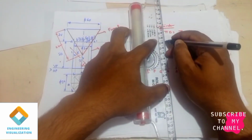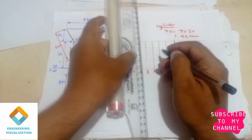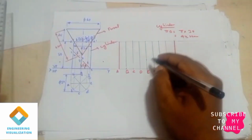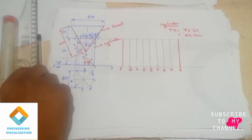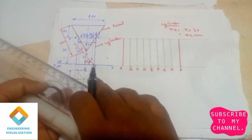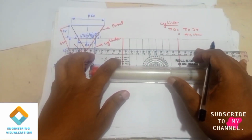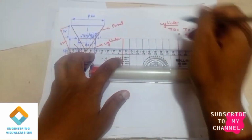Use the scale properly, guys. You need to draw straight vertical lines. Now marking the cut points on this development is easy. Just draw horizontal lines from those cut points. From one, just place the scale like this and draw the horizontal line.